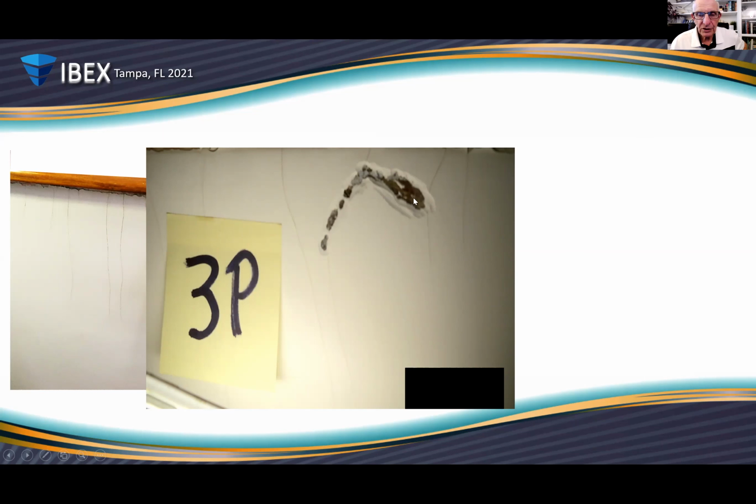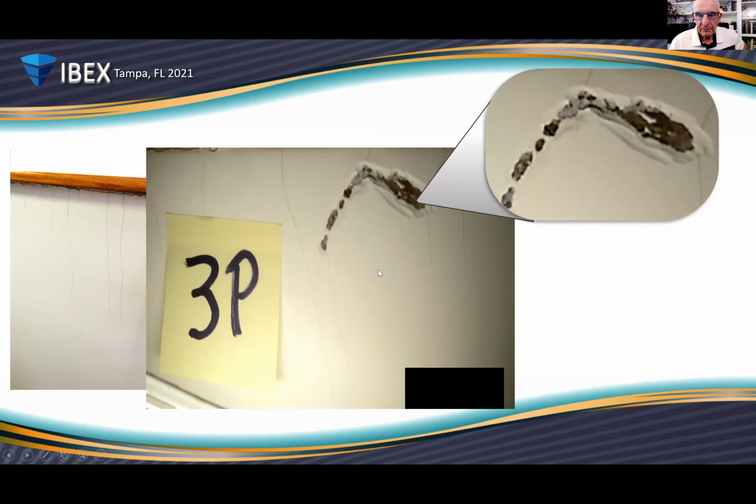Look at the thickness of the gel coat here. You look at it here. We're looking at gel coat that you can measure in 1/8 of an inch, not in mils here. Well, it's no wonder that this thing cracked. In fact, all over the entire boat, the gel coat was mega thick, like we're looking at here, and the entire boat was full of cracks. So not at all surprising when you see something like this.